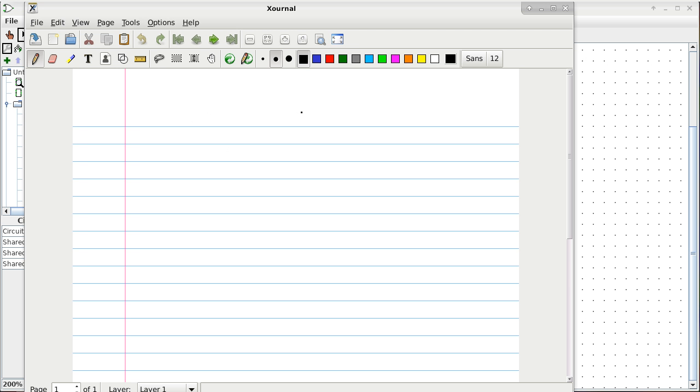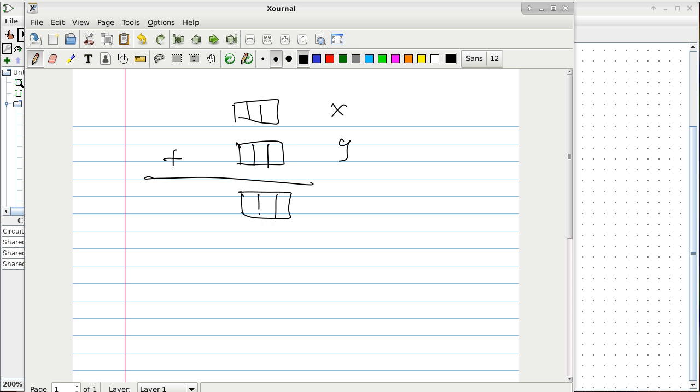Okay, so we are talking about a 3-bit. This is X, this is Y. X, Y. This is Q. This is K. There's another addition here, and this is the actual result that we want, which is the sum. So the question now is, how do we end up with a carry over here. This is our K1. Well, you can have a carry because this one plus this one has a carry. But how do we get that? They both have to be 1s, right?